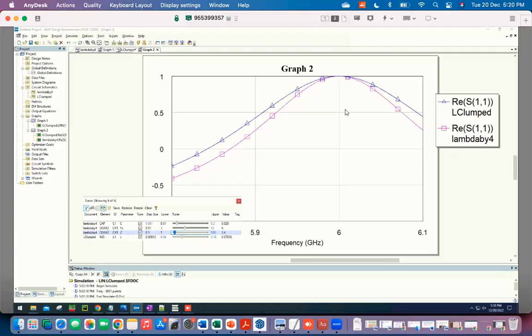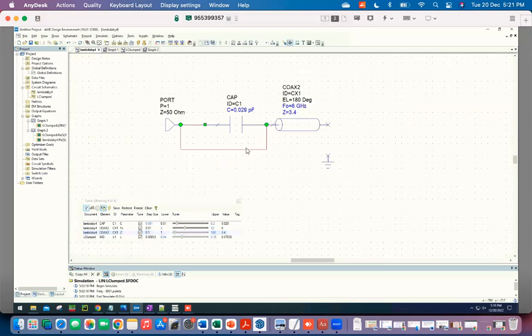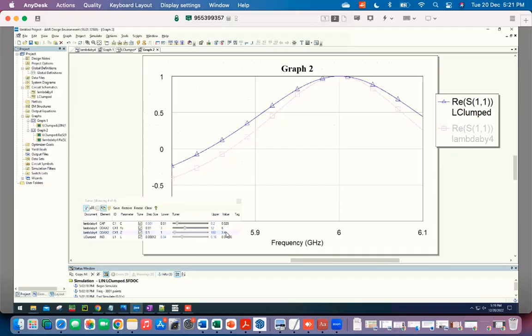No, the Q factor part, that was the part we already discussed. So we know that now the Q factor is becoming better because if I go to low impedance, the effective capacitance is higher. So then R C omega plasma, which is the Q factor. My point is here when I change the characteristic impedance, the resonant frequency did not change. But here, if I introduce the coupling capacitor, then the frequency seems to depend on the characteristic impedance as well.